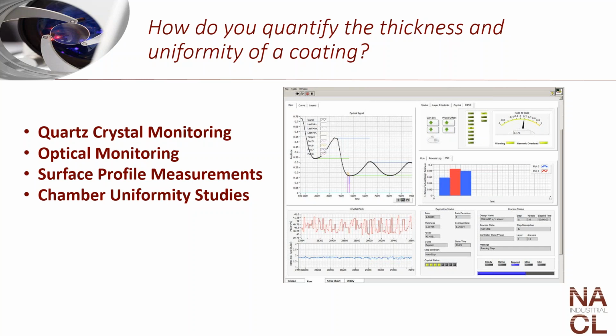The other principle for measuring coating thickness is optical monitoring. Optical monitoring actually monitors the thickness of evaporative materials that goes onto the substrates in situ. So the beauty of optical monitoring is if there's any error factor, be it even 0.5%, you can actually correct within the coating process while you're pumped down to overcompensate for any errors you may have made in layer thicknesses. So optical monitoring is a very important way to make sure that you're providing the best coating. Optical monitoring a lot of times is used in very sophisticated narrow band pass filters, edge filters, laser damage frequency coatings, lots of different coatings that are more sophisticated than your standard maybe 2 to 10 layer stacks.